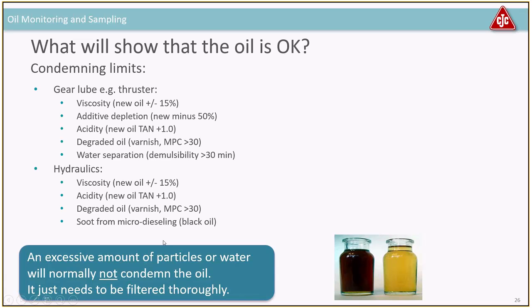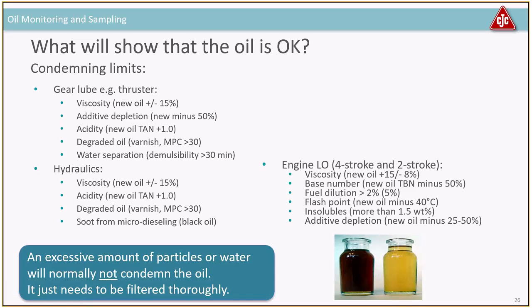So if the oil is turning very black, the oils you can see here, that's an oil that has degraded into this brown. That's a normal degradation. But if the oil suddenly turns black, like grayish black color, it's actually air that is being compressed in a high pressure pump and then cracking or destroying the oil. That you can see quite often in hydraulic systems using these ester-based fluids. So EHC systems, control systems for turbines, have that issue quite often. You may also in some hydraulics test for foam, or you may test for air release and so on. But these are the basic tests.